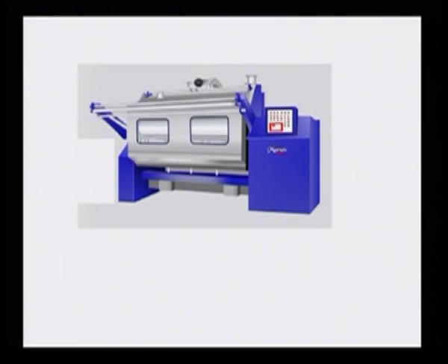And in this, every time the fabric comes in contact with the dye, it is for a short while, and it is a very repeated process. So, at no time is the fabric too much in contact with the dye solution. Therefore, the uptake is very uniform, and throughout the length of the fabric the color will remain the same.